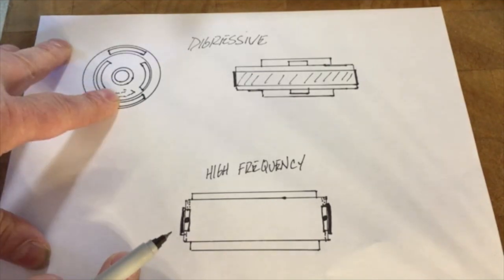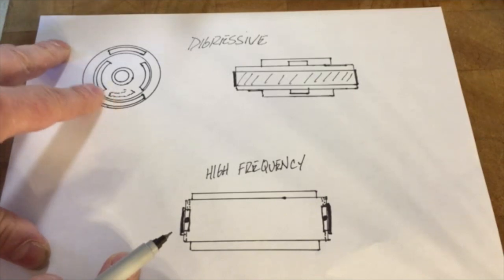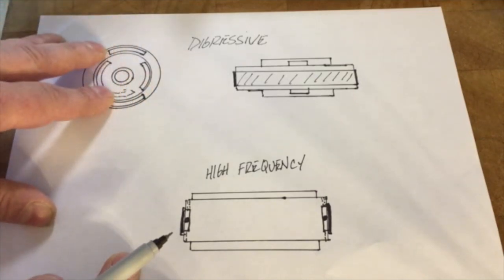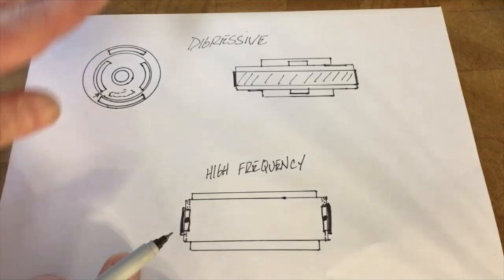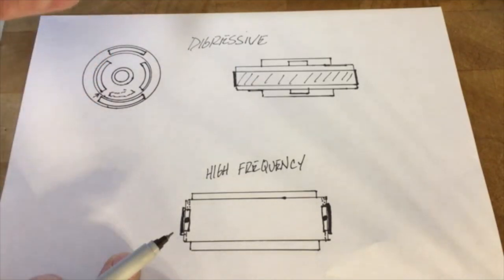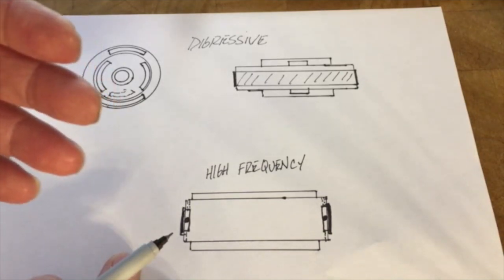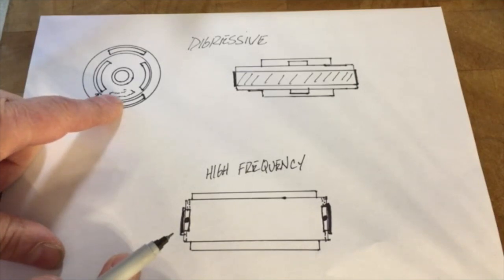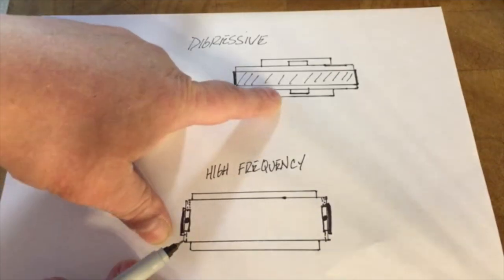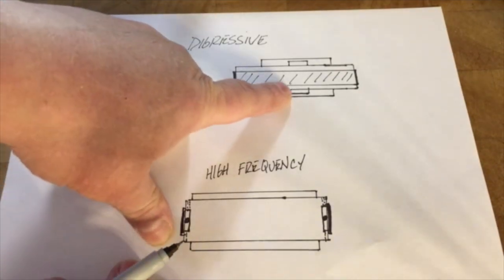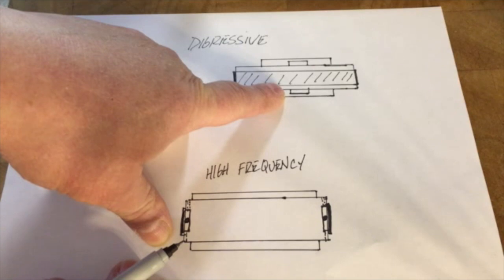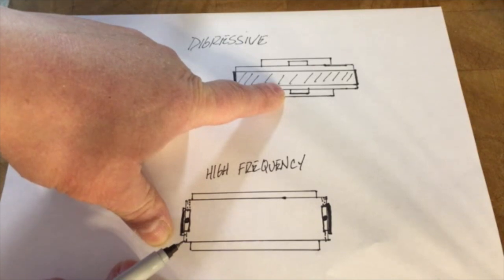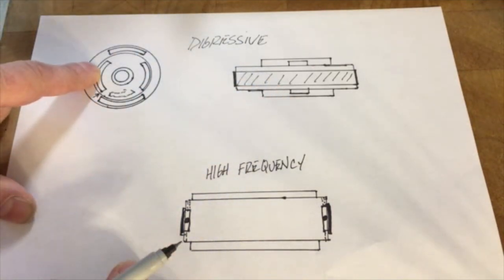So I was thinking about what happens if you put a soft cover plate on there and then you stacked it up and made almost like a progressive valve stack, so as the shock gained speed, you'd still get the control you need, but yet you wouldn't have all that sloppy bleed in there to begin with. Another thing that's interesting with a lot of digressive shocks is that there is an amount of preload built in